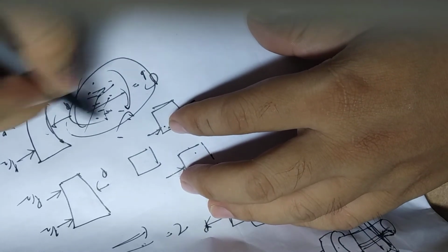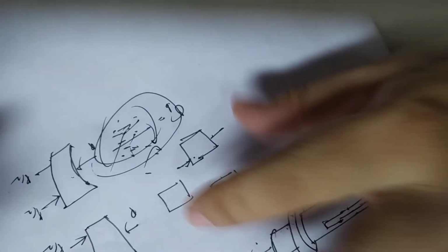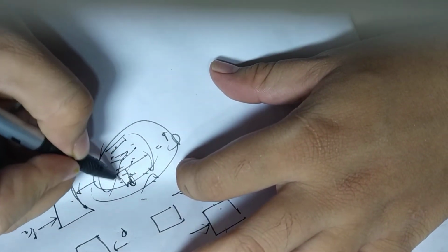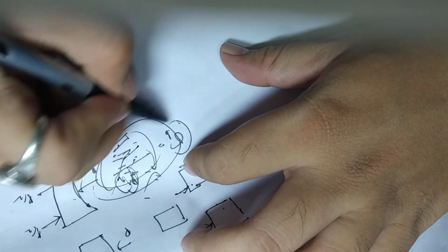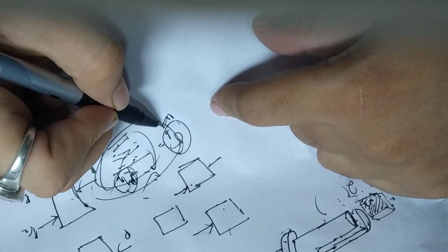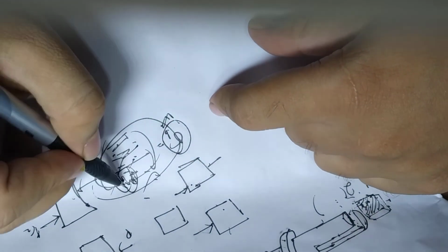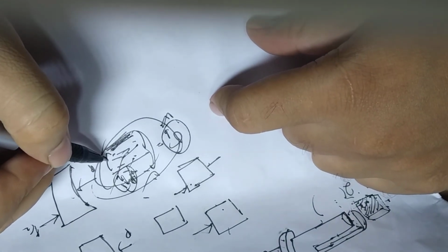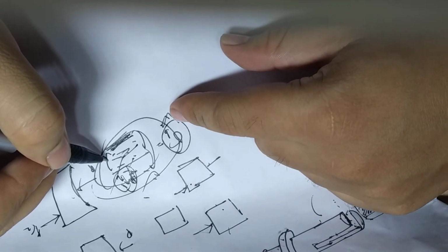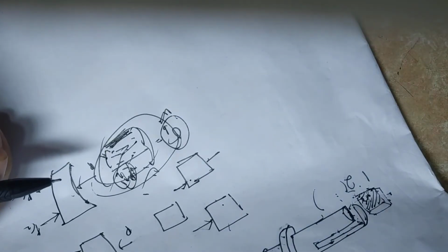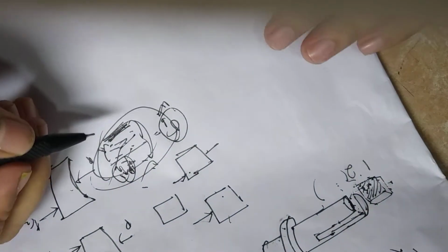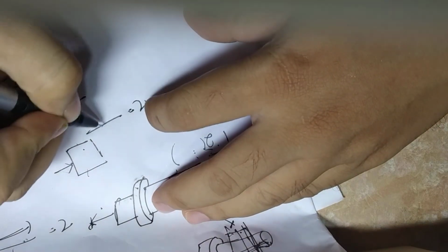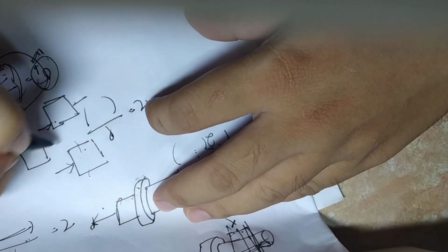Now you see, all these formulas are force by something or moment by something. So we have to find out the allowable stress first, then the moment or force will be given to you, and you have to find the safe dimension to prevent the failure. Understood? That is what we are doing. Now the safe dimension: using that formula, shear stress equals force divided by the failure area in case of complete breaking.